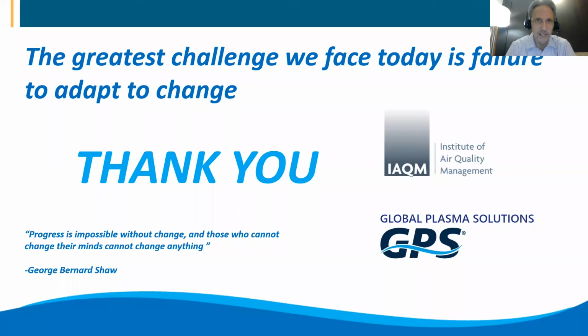That's 99.99997% efficiency, right? And then on top of that, between higher velocities and higher filter efficiencies, many clean rooms will ionize the air to help agglomerate the particles, make them bigger, and make them more quickly and more effectively moved with those higher velocities back to those higher efficiency filters. And in a clean room, you're not going to see 18 to 20 million particles per cubic foot or 700 million particles per cubic meter.